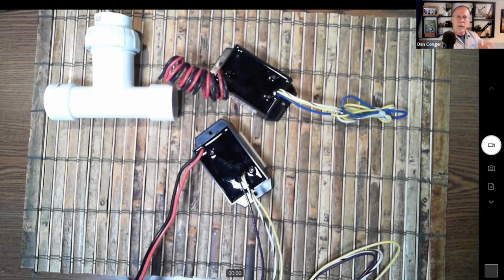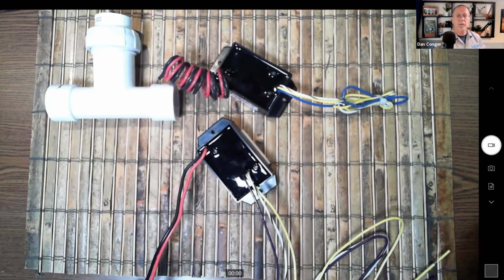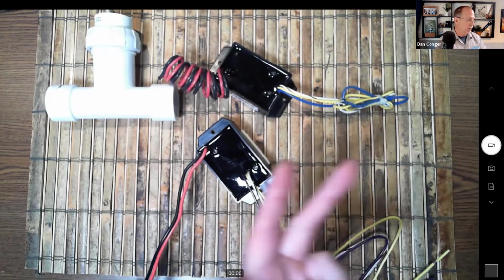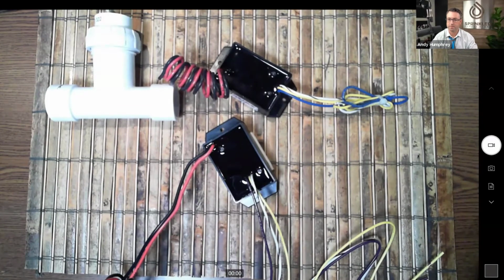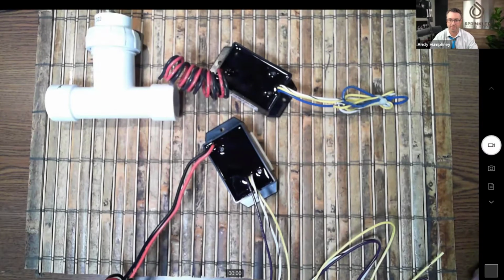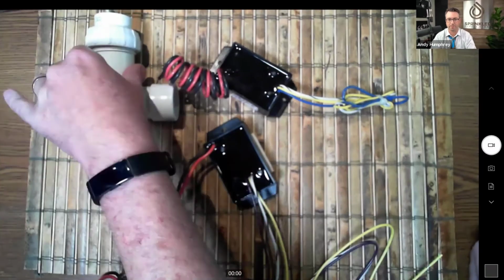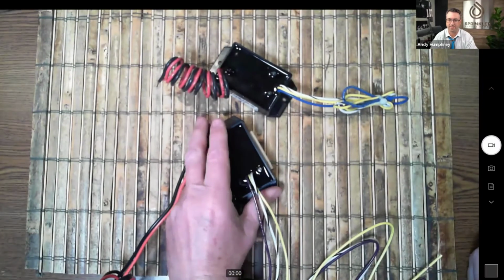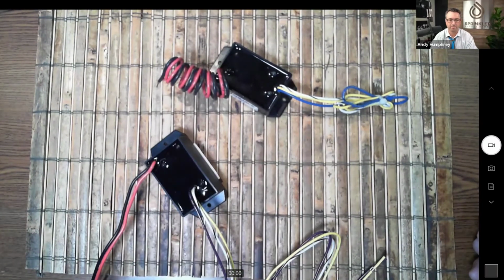And the reason I wanted to bring these up, and the reason I asked that leading question for Chris, is we can connect with most flow devices on the market. So if you have a device that's more sophisticated that we don't offer, like an ultrasonic or a mag meter style, we don't currently offer that. You may want to interface with those, or you have an existing flow device in the ground or a flow device that you like better. Or a pump station that we want to share the flow with. That's true. Yeah, exactly. So flow output. That's a very common occurrence. Why add another flow device when we can just couple on to the output? So you can check with your pump station manufacturer and ask them to provide another output for us.